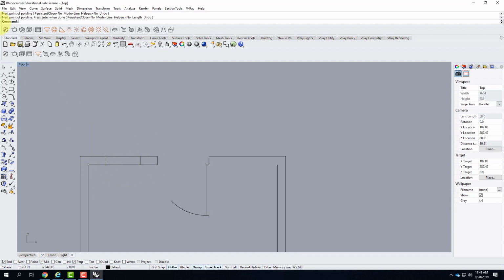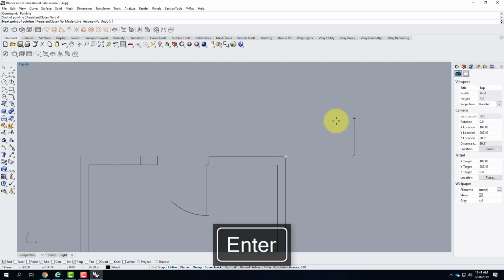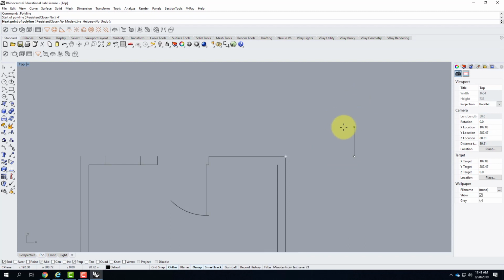So this takes a little bit of practice. Essentially, you hover over a point, you move in the direction you want to go, then you type in the distance for where you want to start. This is something that I really want you guys to practice with today, to feel comfortable with. It's really important as part of your drawing to be able to do that. And it's much cleaner than when you draw little extra tails on lines.